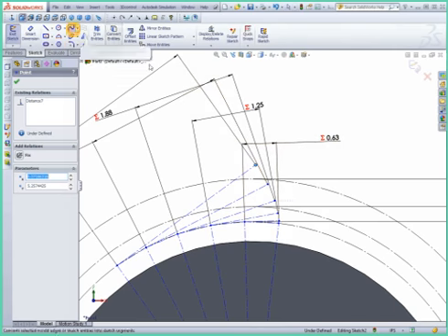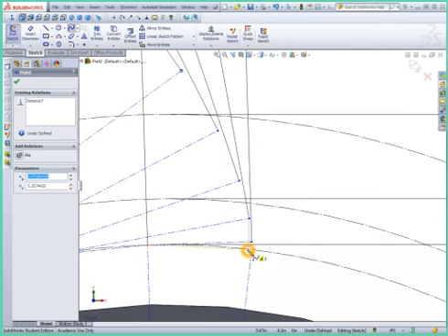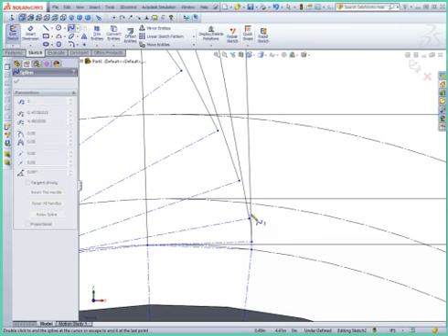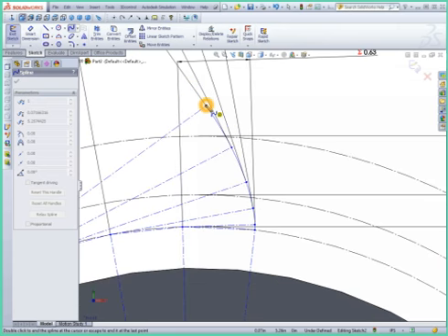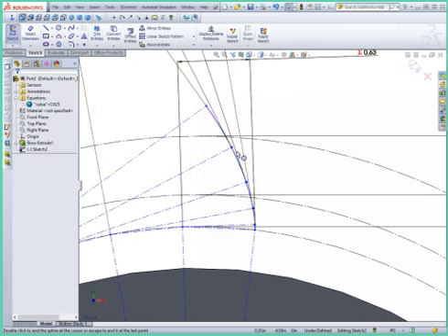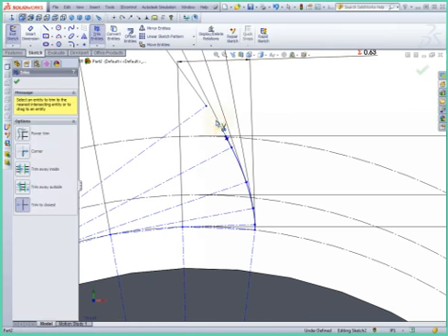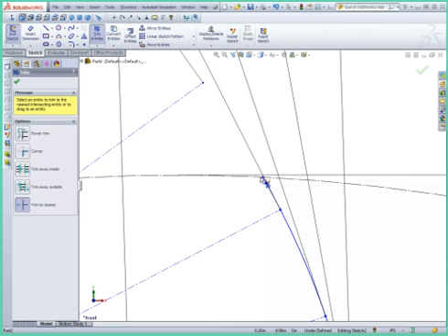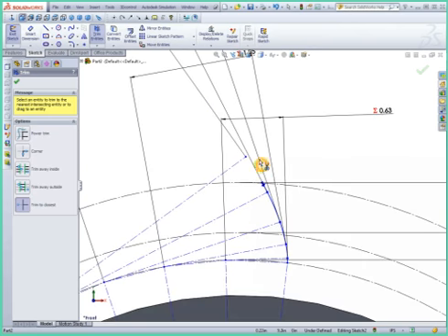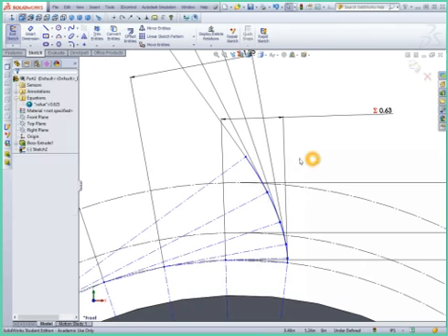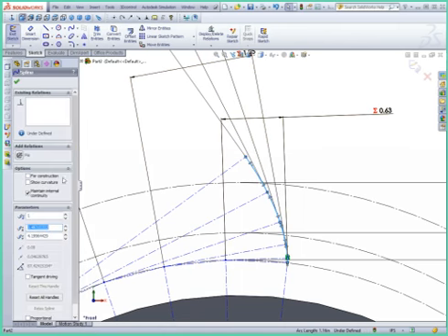So if we choose the spline tool, on SolidWorks we can basically click multiple points along the way and it'll form the spline. And when we get to the end of it, we'll double click to indicate that that's the end of the spline. So now we have a line segment. Now one of the tricks here is that we can trim this and remove that last segment and it'll actually draw the rest of the spline. But if we want it to be dimensioned correctly later on, you'll see, I'll do it again later, we probably want this to actually be a construction line and then we can draw the remainder spline later on. So I'm going to make this a construction spline.